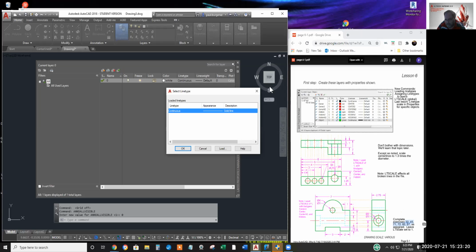Probably time I remeasure this, but I vaguely recall it's like 700 bytes of data, less than a kilobyte. So if you load all the line types, even if you don't use them, just loading them to populate your menu is going to swell up your file unnecessarily.